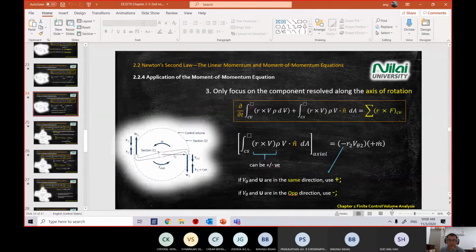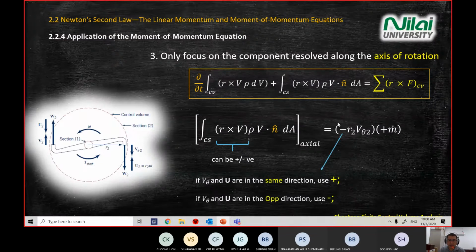There's a slide just now, this one. Just now I explained why there's a negative here. Because if you look at the diagram, V2 is our flow, spray out from the head here. Direction is this way. However, when the water spray out, we know that our arm will be moved anti-clockwise. So we get a negative sign here. So meaning like for every application, it has to be negative, since when it is switched on, it will always move the opposite direction to the water. Correct. Yeah, correct.